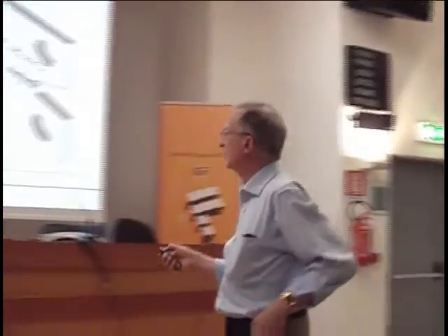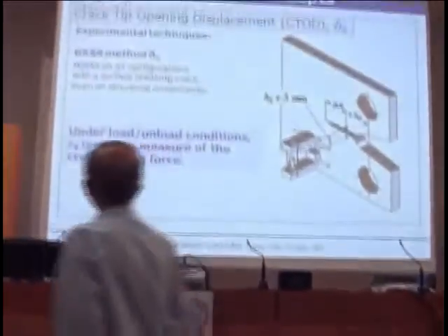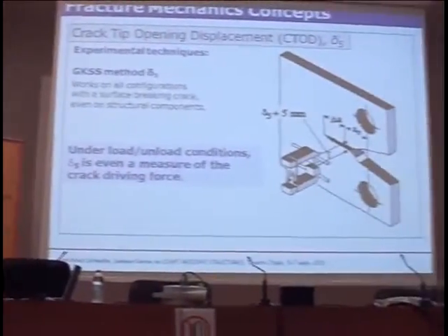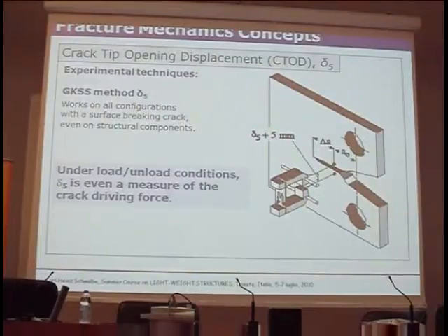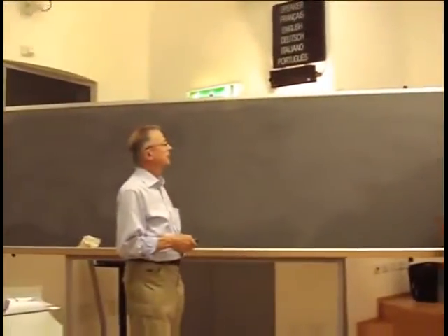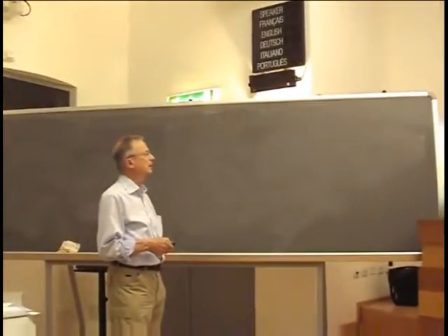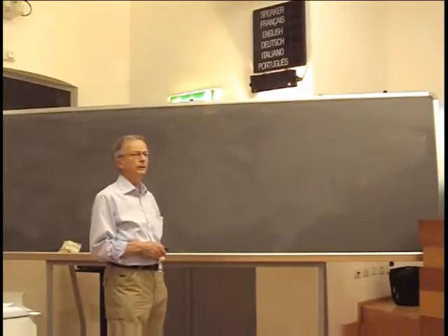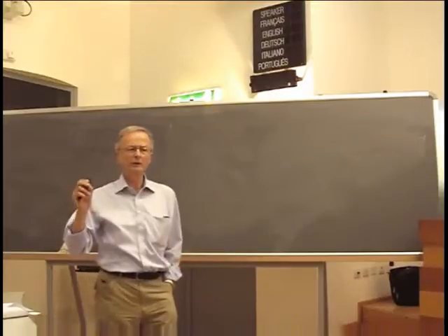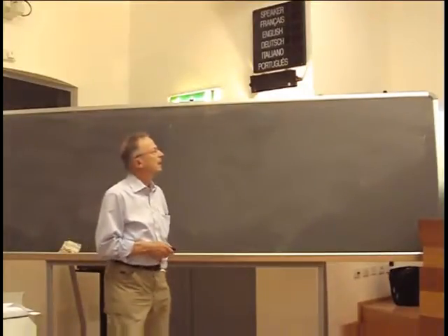And so, like I said here, you can do it in all configurations, including structural components. We did tests on little pressure vessels, and it worked beautifully. That's what I just said. Under load and unload conditions, you can measure it as a crack driving force. Just measure displacement. This is the crack driving force.